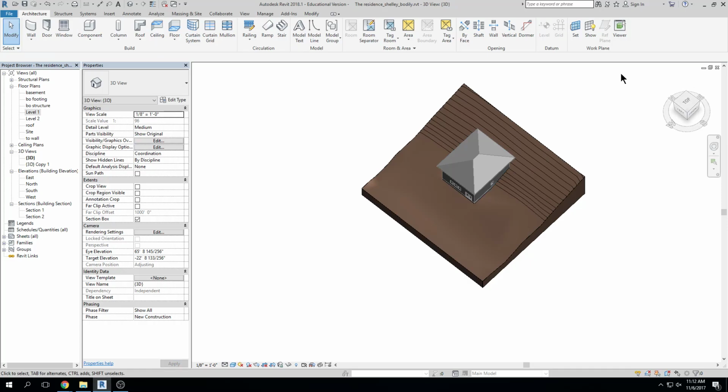So when I tried doing that on mine, it was just grayed out when I selected everything. It wouldn't let me change it. So if you select anything other than geometry, like a CAD link file or a dimension, it won't allow you to change everything to it. So like any furniture or whatever that I dropped in? Furniture should be okay, but if you grabbed an elevation marker on accident or any type of annotation, anything like that, then it won't allow you to do it. Okay, yeah, 'cause I had to go through and select everything. It's a pain in the neck.